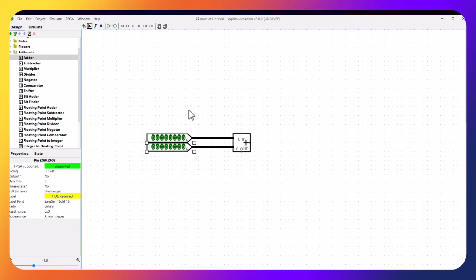Okay, so the same goes for the output. If I go ahead and connect, you will see a complaint. So I'm gonna fix this one, make it 8 as well. Alright, so now I got everything set, so I can go ahead and use it. Let's run the simulation. So let's say I'm gonna add 1. This is 1 in binary plus 1 0, which is 2.